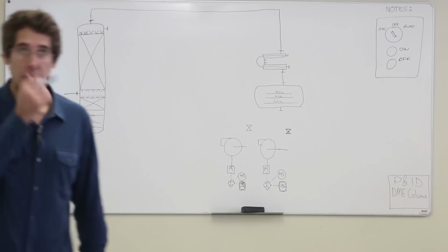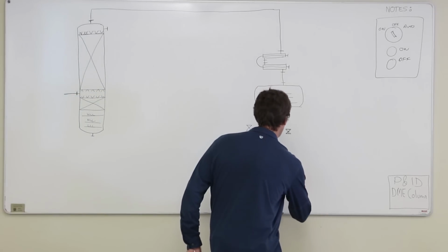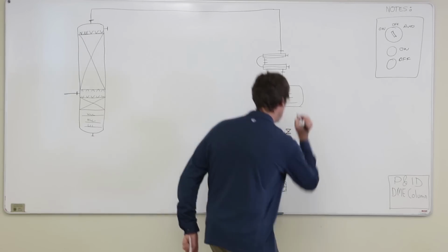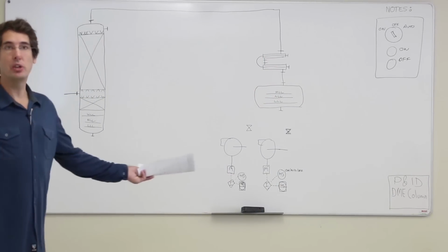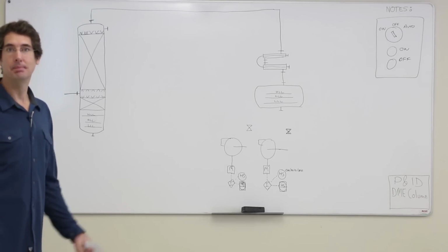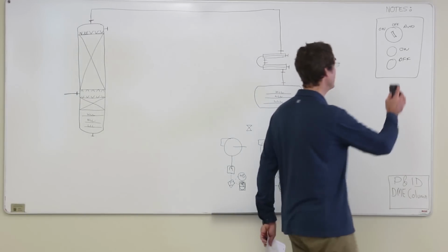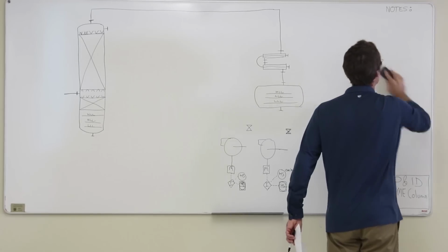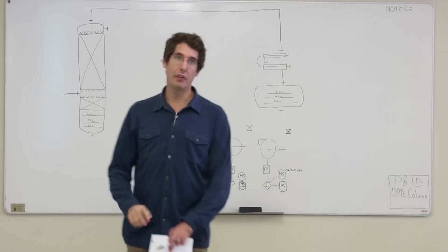Okay, so if we were to draw that on the P&ID, how would that go? You can either put on, auto, off on the P&ID, or you can just assume that it's there because you do it for every single pump. So how about if we put it on, and then it makes it more clear? Sound fair? Okay. But will we have to do that for every single one? We're going to have to do it for all of them.